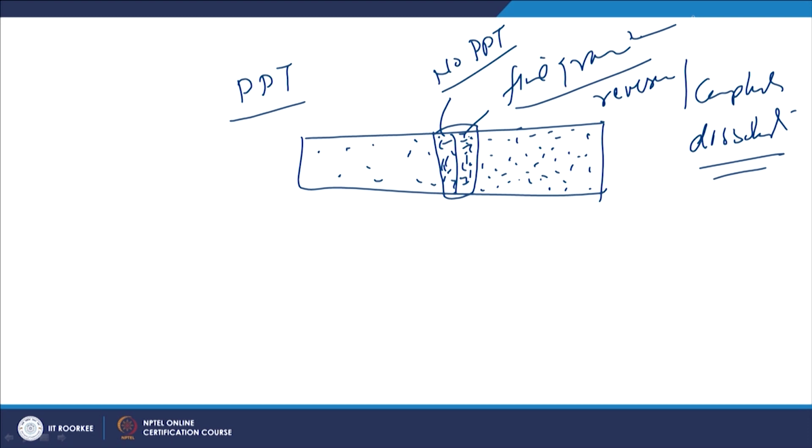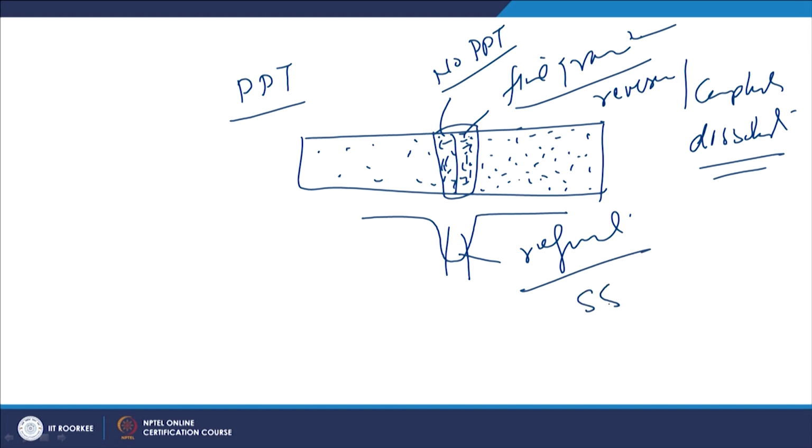In this situation, if we try to just see the properties of the weld nugget area, then we will notice that despite the refinement, there has been a sharp drop in the weld metal hardness and weld metal strength. So, here there is a contradiction: despite the refinement we are getting a reduction in strength, because this metal was primarily designed to have its strength from the precipitates, and if these precipitates have dissolved, then refinement and solid solution strengthening will not contribute as much as was designed for the precipitation hardening.